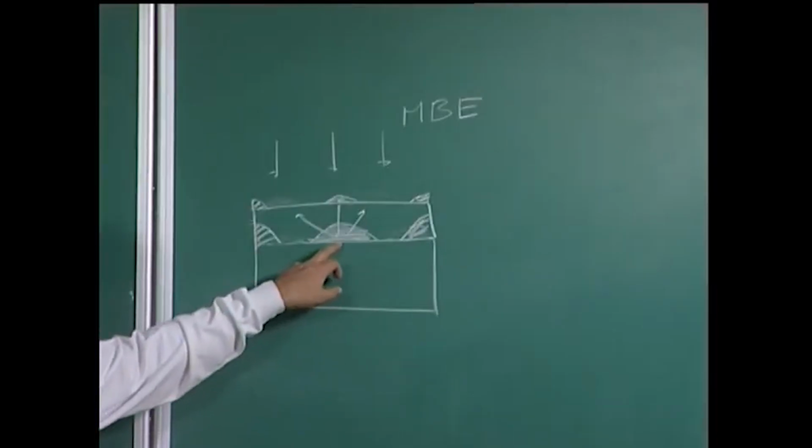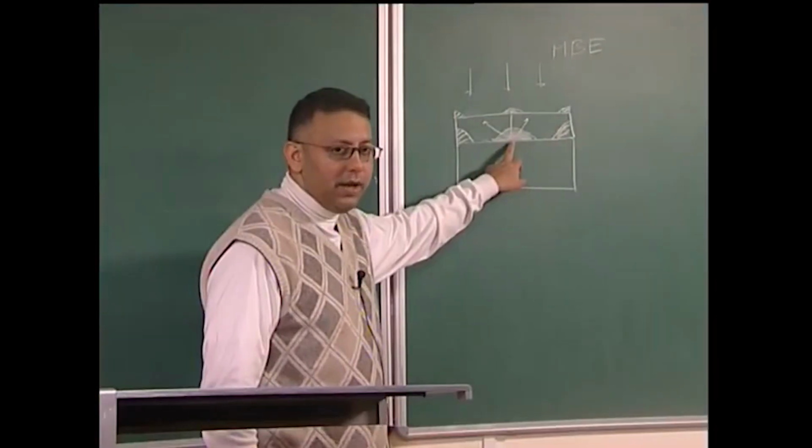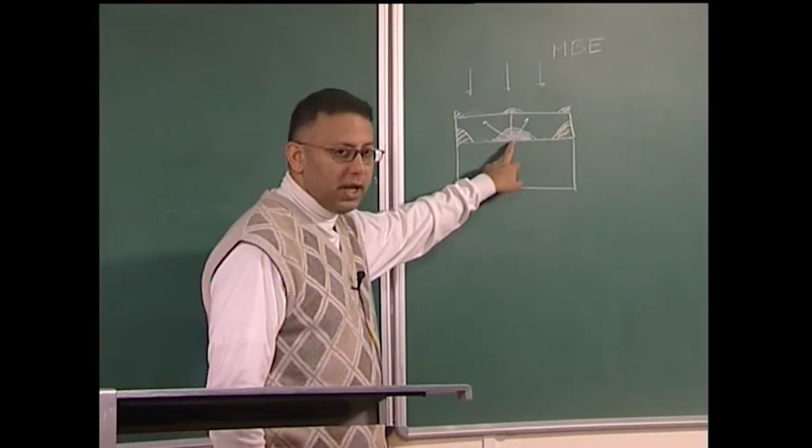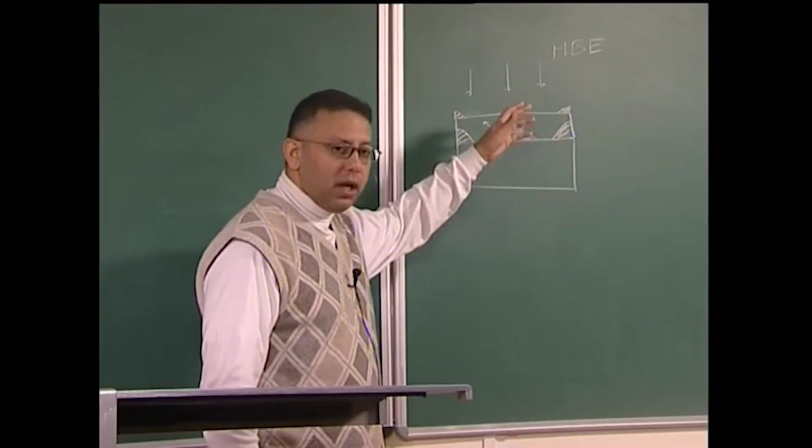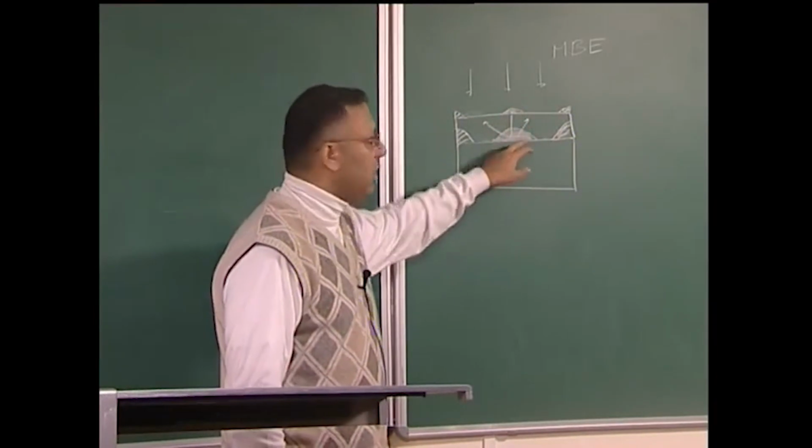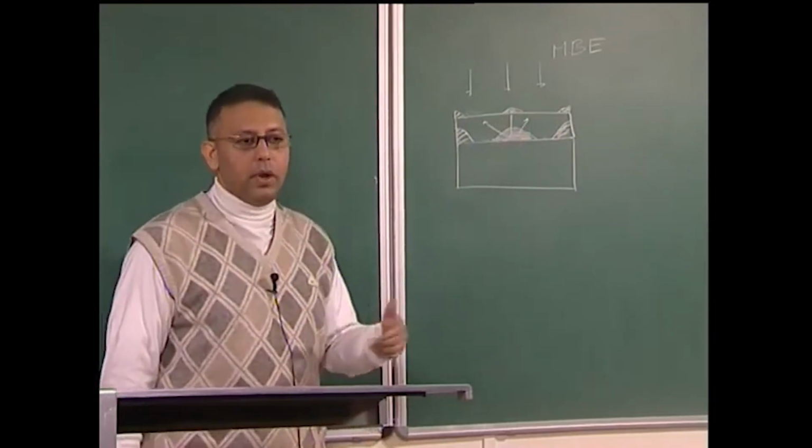So, there is a volumetric term which is the coherency stresses, which is the additive term, in other words it is opposing my nucleation here, but there is an interfacial energy term which is low, and therefore, it prefers to have a coherent interface. And later on when the system evolves with time, you will notice that what might happen is that there may be interfacial misfit dislocations which form, which actually partially relieve my coherency stresses or the epitaxial stresses, and at even larger growth you may notice that this interface may actually become completely incoherent because of the presence of many dislocations.